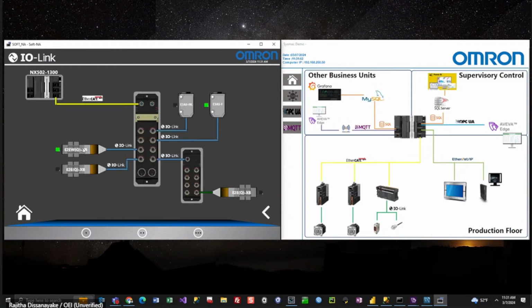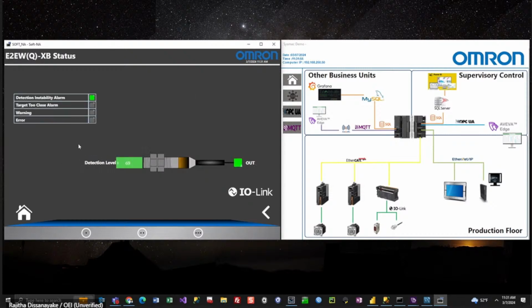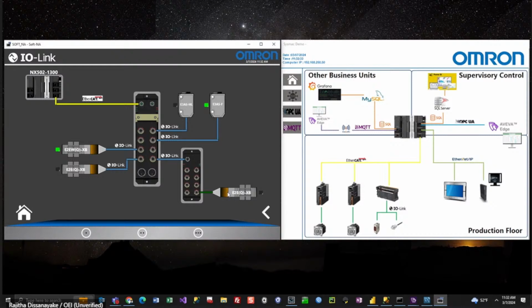This is valid for even a proximity sensor. For example, I have this proximity sensor set so that the object that it detects is not totally on top of the sensor. It is maybe quarter way, so that the sensor is actually detecting the object, but it's not actually getting a stable signal. So it's giving me an error stating that I'm detecting something, but it's not stable. So you can look at all this data and say, okay, well, it is time to maybe adjust the object that the prox sensor is reading, or use it for your predictive maintenance schedule as well.